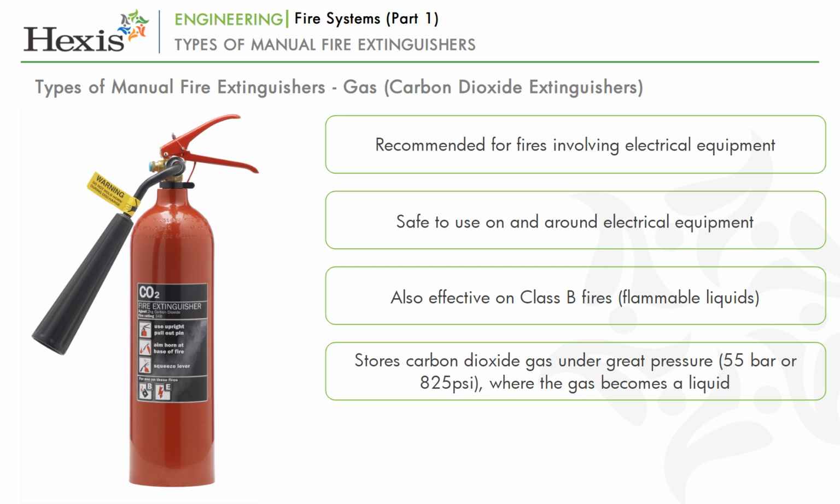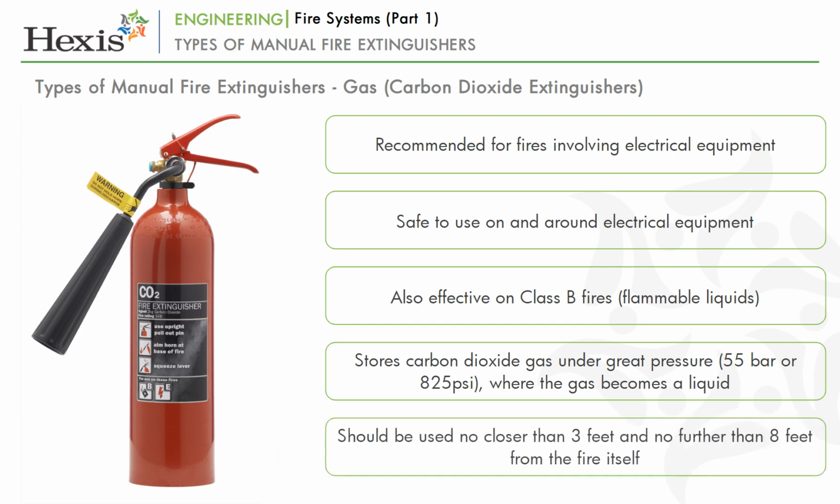This process is so fast, it can cause ice to form on the horn, so never hold a CO2 fire extinguisher by the horn to avoid freezing your skin. To be most effective, a carbon dioxide fire extinguisher should be used no closer than 3 feet and no further than 8 feet from the fire itself.